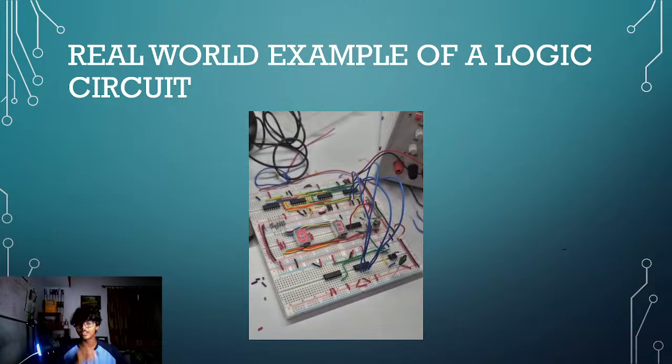Essentially what it does is it counts up. It's like a traffic signal light. It counts up, so it goes from 00 to 01 to 02 all the way up to 15 because it's a 4-bit counter, and then it goes back to 0 again, and it does it again with a frequency of 1 second, 1 hertz. So it's like a second counter basically.